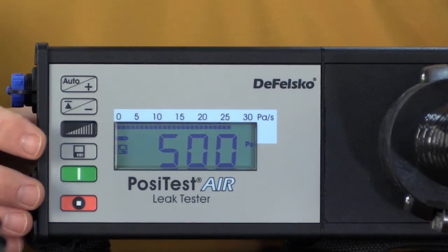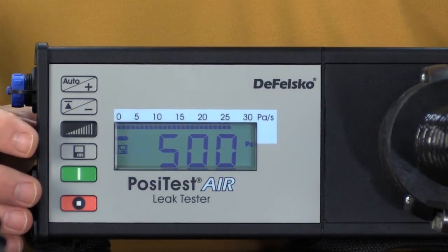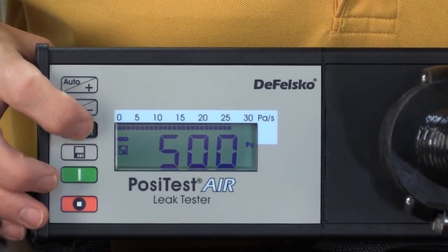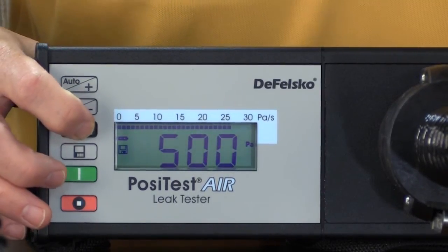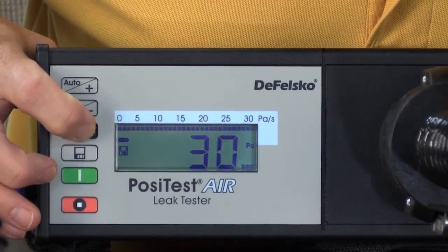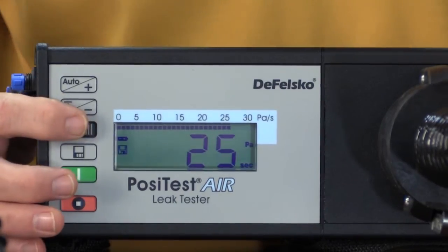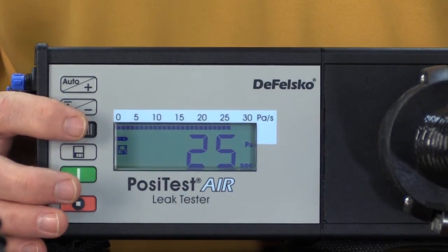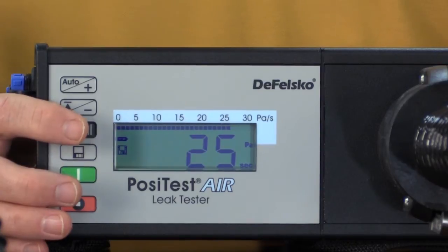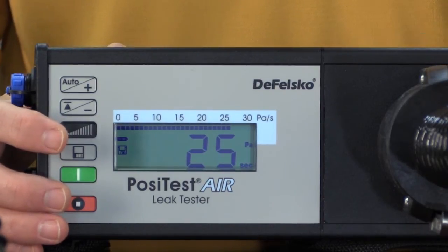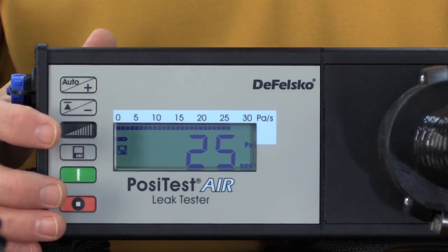The pressure differential is created by really adjusting the fan speed. That's what pushing that button does. The rate of depressurization is adjusted by pushing this button. It changes the rate in increments of 5 pascals per second, and the common setting here is 25. We recommend the use of the auto mode, particularly when starting up. If you don't use auto, then you have to adjust the pressure differential manually and the rate of depressurization manually as the test is being accomplished.